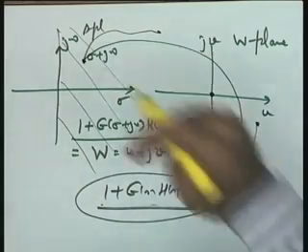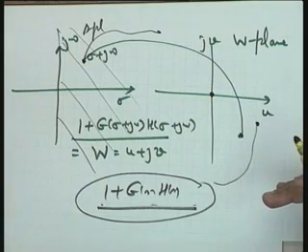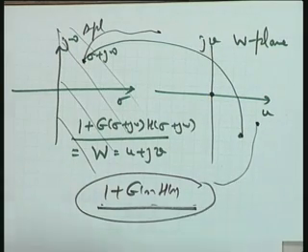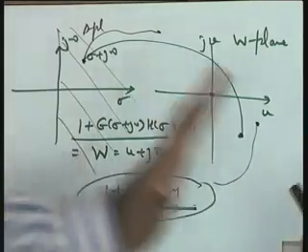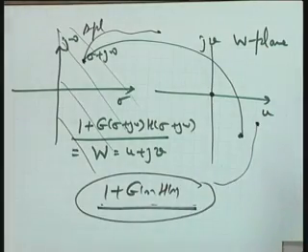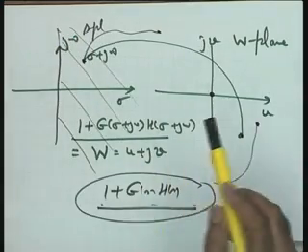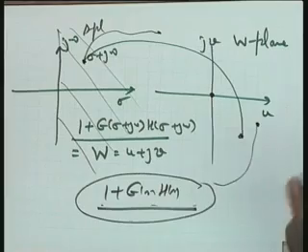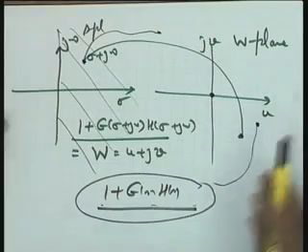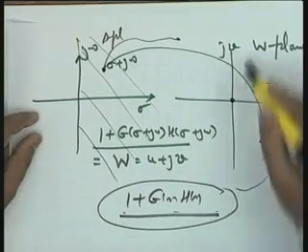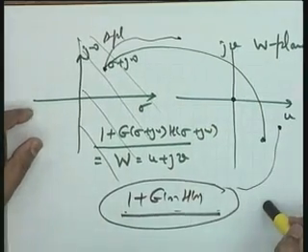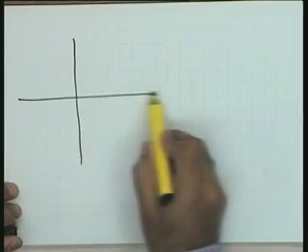So, you see that if one-to-one mapping is to be obtained, it becomes a very difficult proposition and the Nyquist stability criterion will lose its importance. We are really not interested in one-to-one mapping quantitatively. We are interested in one-to-one mapping qualitatively only, because our interest hinges around the origin of the W plane. Okay. So, you see that any contour in the S plane will map into a contour in the W plane. This also should be clear. Okay. If this is appreciated, then a question will follow.